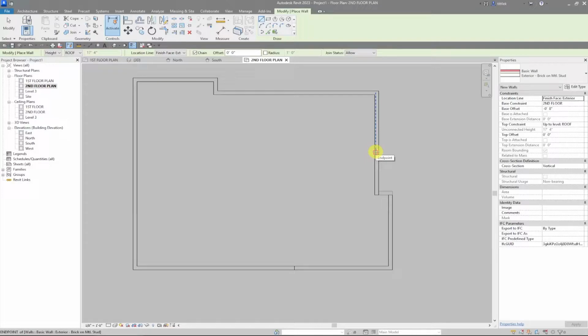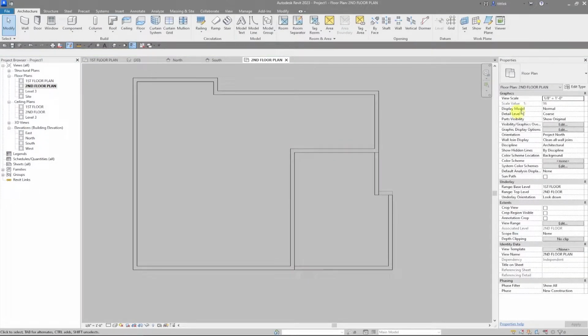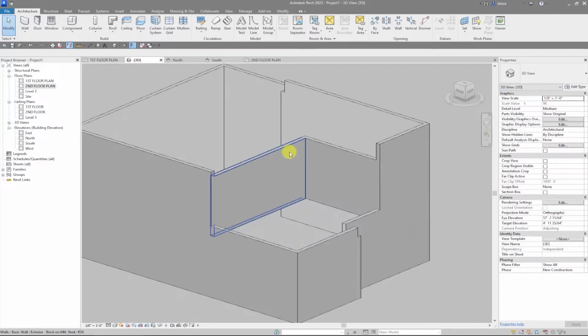So I'm going to do this wall right to left because it's going to place the exterior towards the bottom of the screen. And I can even grab that inference. I don't even have this exact location set, and I did not follow my Revit creation method, which is bad, so I need to check my 3D view. For now these just went up to the roof level because I didn't check those constraints, but that's fine.